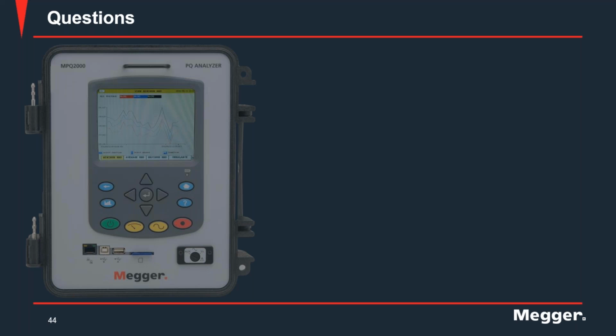What will happen is the MPQ won't start running the test until 10:10 a.m., and then you get your first set of values at 10:20 a.m. So all your RMS data points will be at 10:20, 10:30, 10:40, and so on. That gives you a standard format as far as data timestamps are concerned, and that helps with synchronizing with other systems or with data files from multiple recorders. So if you're recording data in multiple locations, you can compare data files by comparing the data points recorded at the same times.